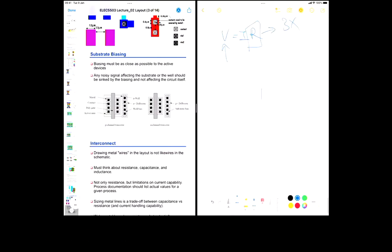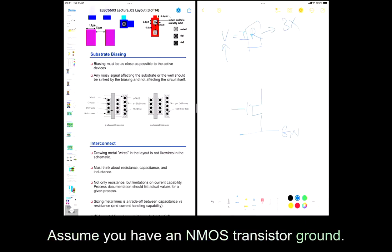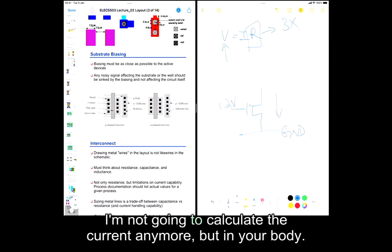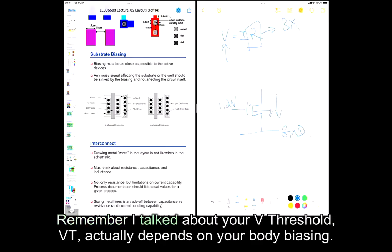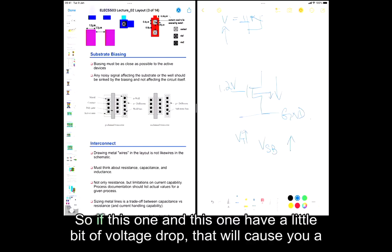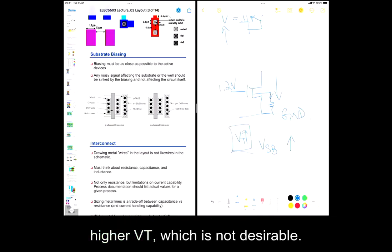Same for your substrate. Assume you have an NMOS transistor with ground connected to this 1.2 volt. I'm not going to calculate the current anymore, but in your body, remember I talked about your threshold voltage VT actually depends on your body biasing. If your VSB is large, then there could be a problem of increasing your VT, so you have a slower transistor. So if this one and this one got a little bit of voltage drop, that will cause you a higher VT, which is not desirable.